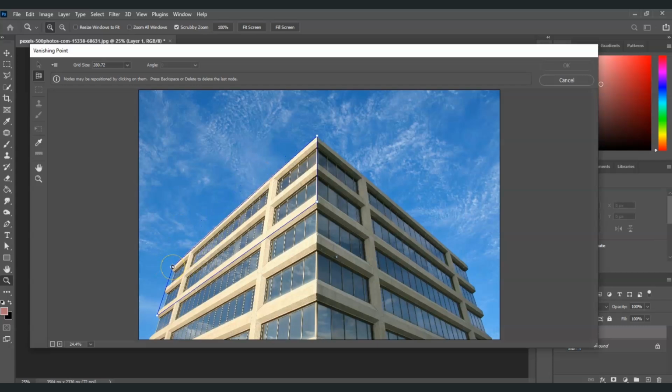here, and here. Okay, now the next step here is I'm going to press and hold Control, then click and drag this side to create another grid line on the other side of the building. Something like this. All right, there you have it. Now the next step is we're going to extend these grid lines. So with this right grid selected, I'm going to click and drag it on top to extend that into this, right? And also to the other side, click and drag this top point to extend, all right?